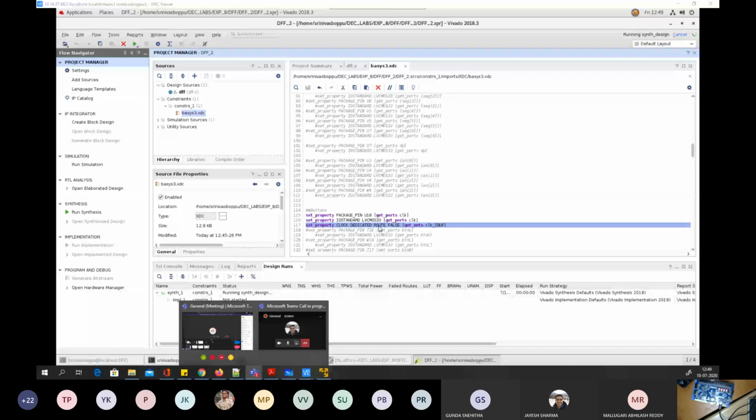By default, Vivado thinks that whatever follows posedge in your always sensitivity list will be a clock. It will try to use dedicated buffers and route that signal, and then it's tough for us to reach this button C. We just wanted to disable that. In a general design we shouldn't do it, but for a simple single flip-flop we can do that for our purpose.